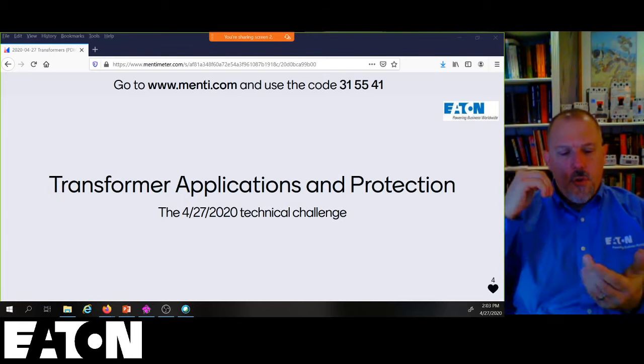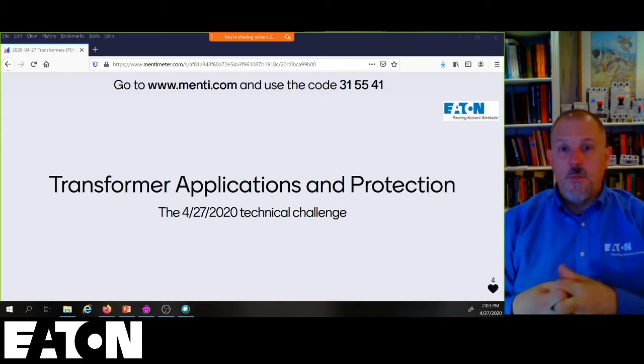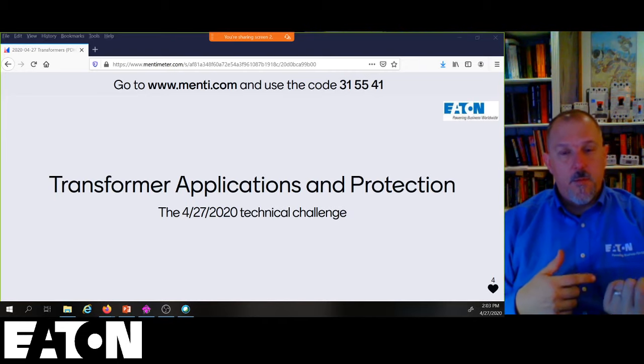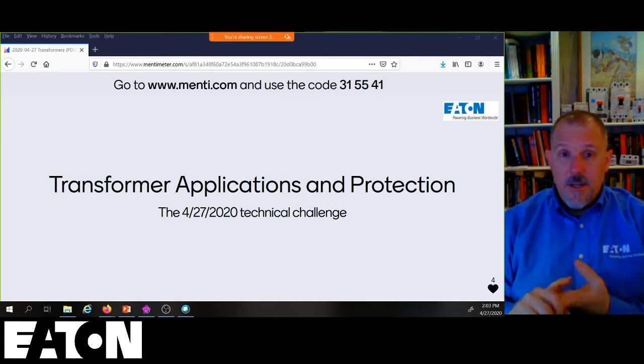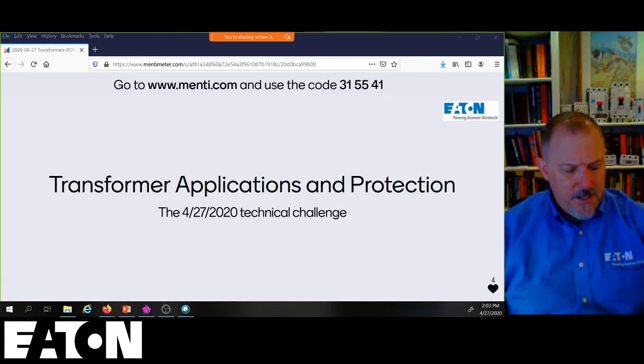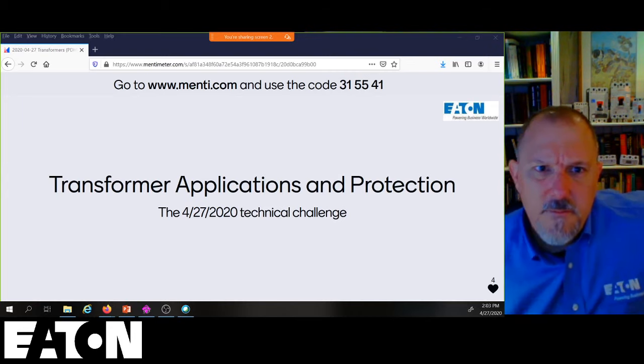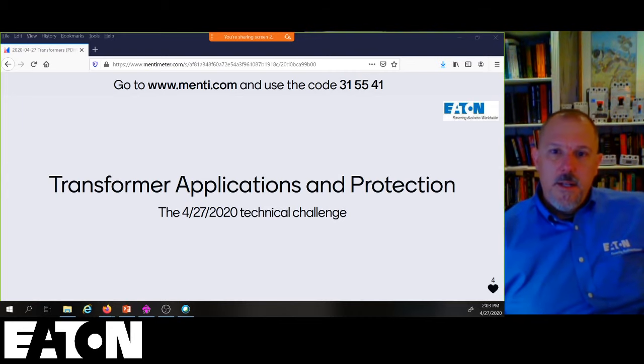You don't have a main overcurrent protective device in that first panel board; you remove it and put it in the transformer. I'm not sure what we charge for that transformer. I'm not a numbers guy from a sales perspective. I'm a technical guy. If you did a main breaker outside, you might increase that cost, but I'm not sure by how much. So just keep that in mind.